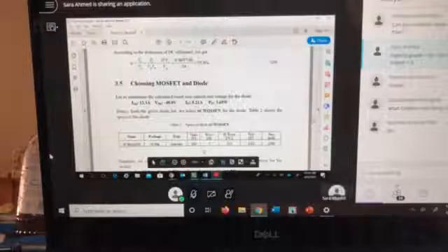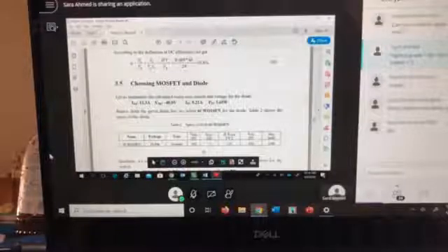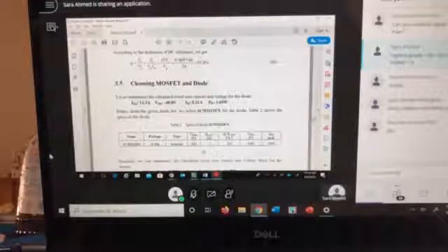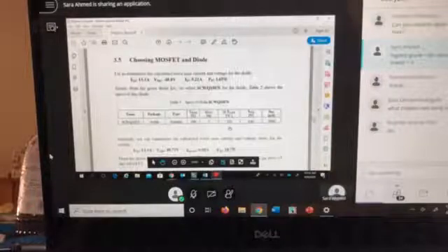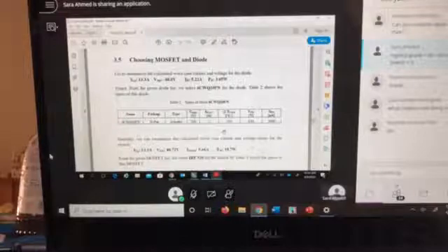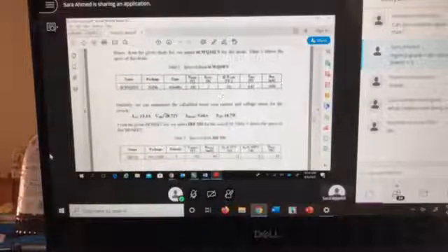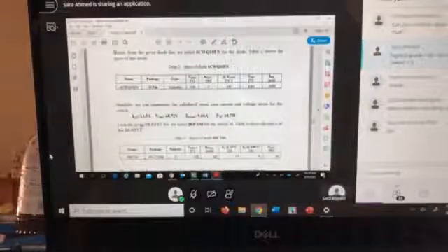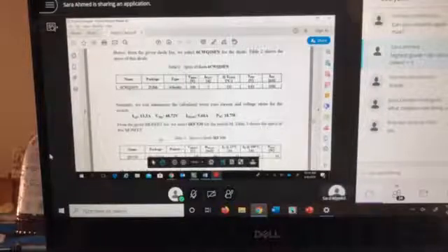There was other cases which have like 10 or 20, you can choose that. You don't want to overkill, which means I don't want to choose 1,000 volts. I want to choose something that's in between or close to 2 times the voltage and 1.5 times the current. The same thing with the MOSFET. So I chose the values that I calculated as my worst case scenario. And then based on those 3 values, I went and I chose something.